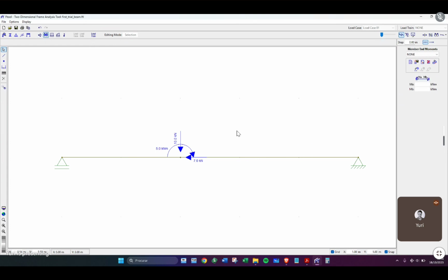And you can also define bending moments if you want. For example, I can select the sidebar and I will put the moment, for example, let's just put -3 kilonewton meters. I'm going to click done, and here I'm going to put -3 on one side. Click here, and on one side you have the nodal bending moment applied to the support. If you put +3, it's going to change directions, and if you apply -3 to the other side, you're going to apply another one here. So this program is quite interesting because you can pretty much define every type of nodal force as you like. And the program is very friendly, as you can see.